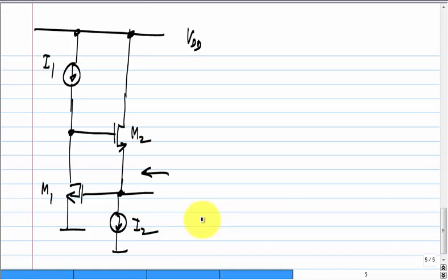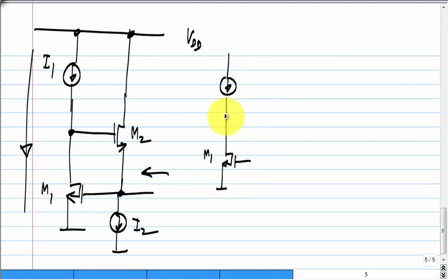So, what happens is that if M1 is in negative feedback, and the current through M1 is fixed, the current through M1 is I1. And you are told that GDS is 0, that is lambda is 0, which means that the current depends only on VGS. First of all, it should be easy to convince yourselves that M1 is in feedback. The conventional circuit for biasing M1 at a current of I1 was just to connect it that way, but we do not have to make a connection of that sort. We can take any stage which has a positive incremental gain and connect it. The only thing is after we make the connections we have to make sure that all transistors are in saturation.